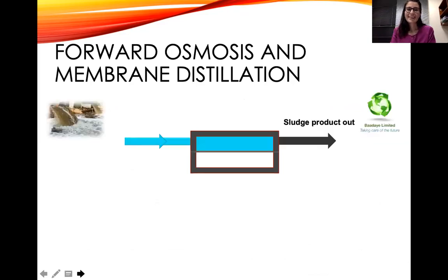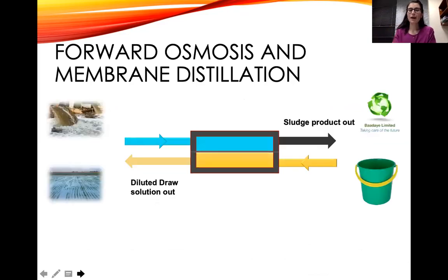Okay. Right, so this is my PhD research, where I combined two membrane technologies to treat wastewater. So let's say that there's wastewater or sludge going on the one side, and in this particular case, I'm using, let's say, a fertilizer, because it has an osmotic potential. I'm using that as a draw solute. There is a membrane in here.